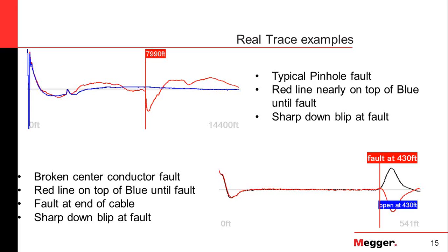Now later in the fault locating process, you will turn your thumper on, and the whole point of the arc reflection is to quickly prelocate your fault with a single shot, and then that will minimize the number of thump impulses you have to put into the cable. To summarize, today's fault locating process, if done properly, is not going to cause any additional damage, or very little additional damage.